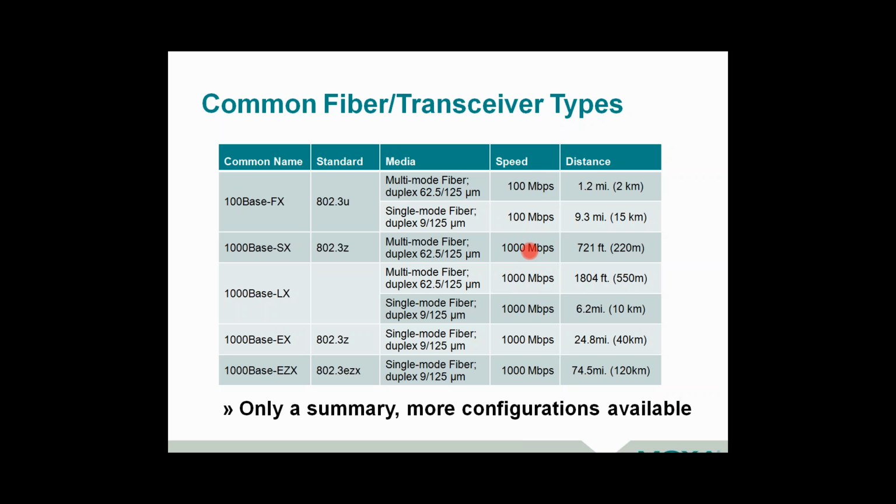And then based upon what you're trying to achieve, there are different standards for the optical transceivers to be able to drive that over a longer distance, right? So when you look at that, first look at speed and then look at the distance you're looking at. This is going to help you select which type of media converter you're going to use. For example, and I'll go into that in a following slide, you'll find a terminology called multi-mode versus single mode. This is a characteristic of different types of cable that you might use.